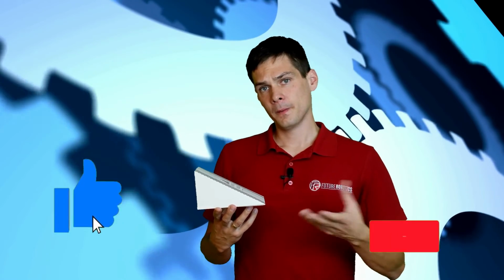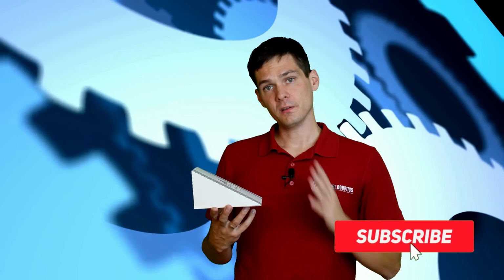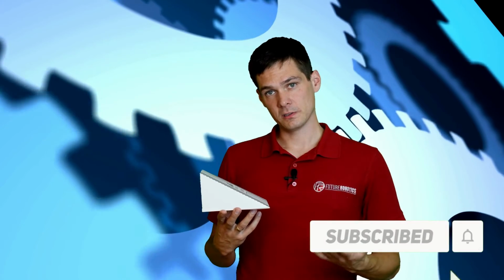You can do all of that when you will be teaching your base frame. The way how we teach the base frame is pretty simple. It's kind of like we teach the TCP. Very important, you need to have the TCP taught before you can teach the base. Super important. So basically what you're going to do is you're just going to define where your 0 is of the base frame. So basically where the origin of your base frame is.